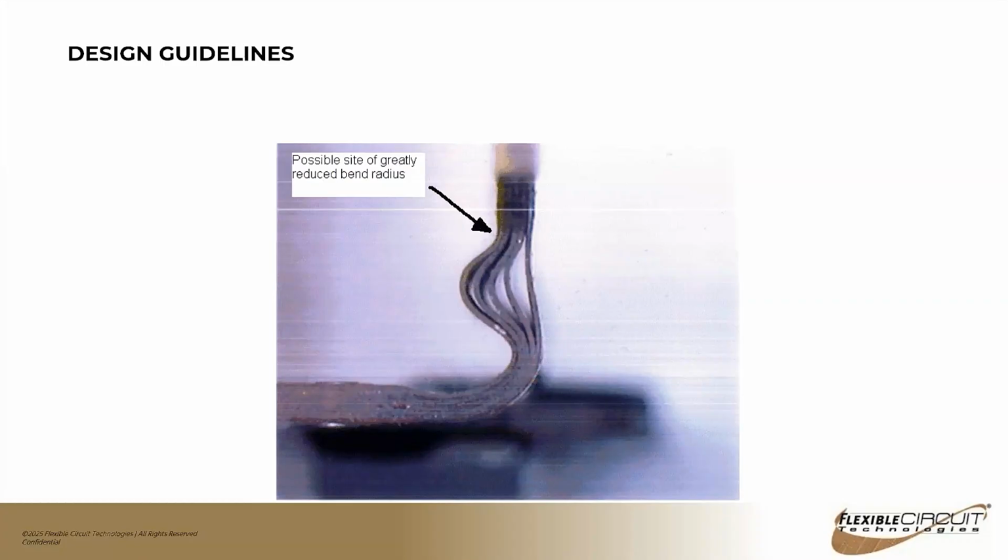There are some design constructions, for example a book-bound part where the flex straps are at different lengths, so everything will bend and be basically the same length in the formed state. However, those constructions can come with higher tooling cost and overall higher cost because of what's involved in the manufacturing of a book-bound circuit.